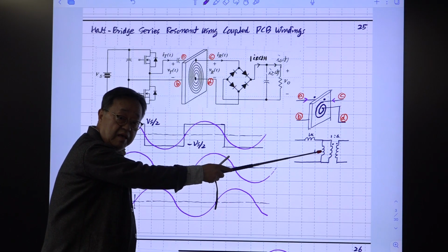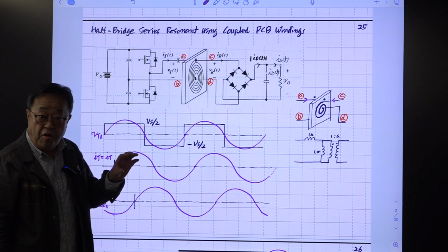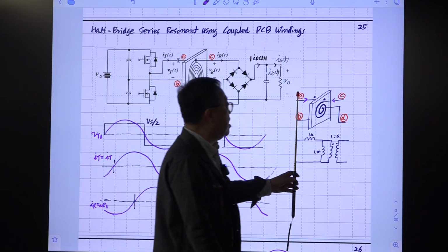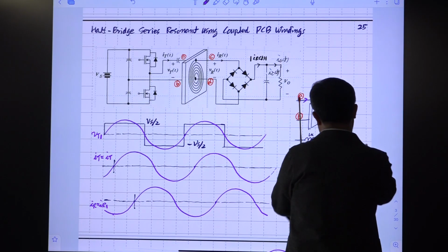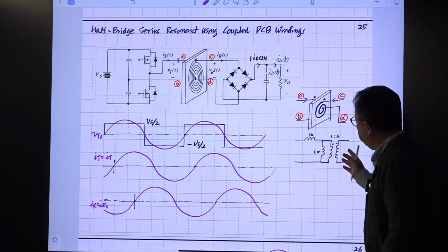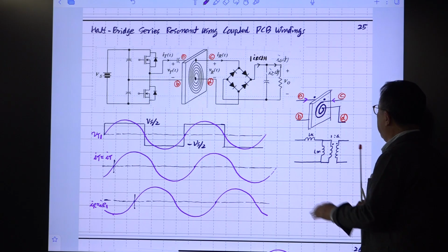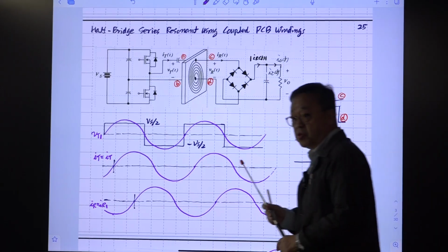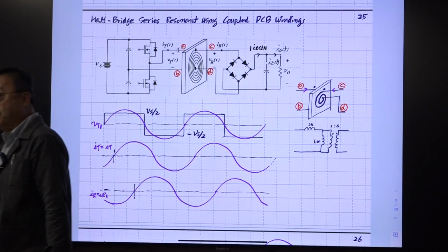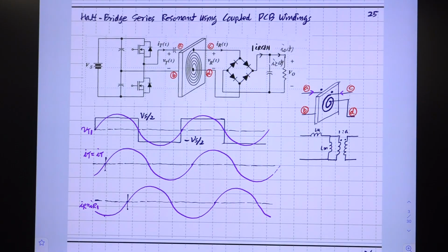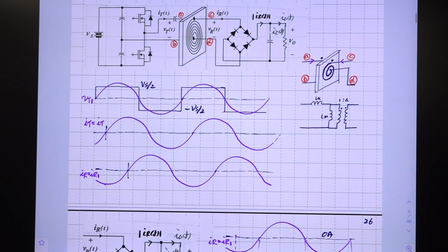It's 1:a, where a is some number different from 1, because this structure is not symmetrical. If everything is symmetrical, it should be 1:1. But all the parameters appear only on the left side of this ideal transformer, so it should be different from 1. If that is 1:1, that guy is lying.